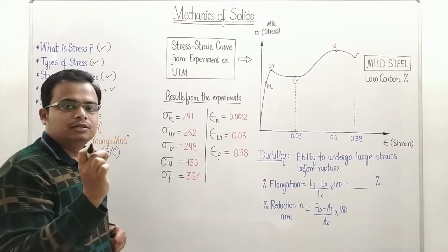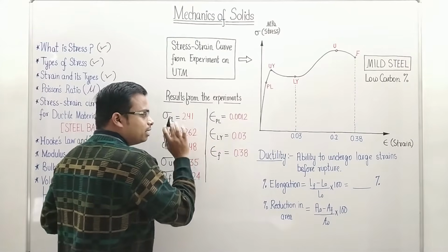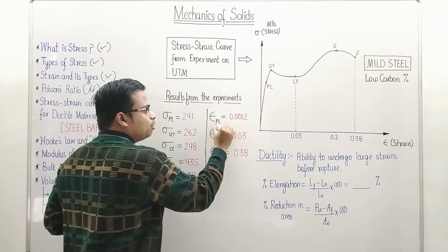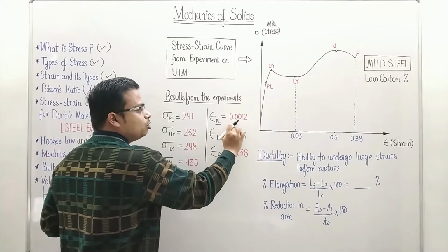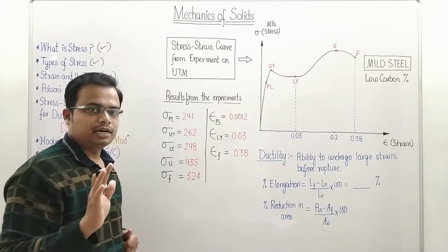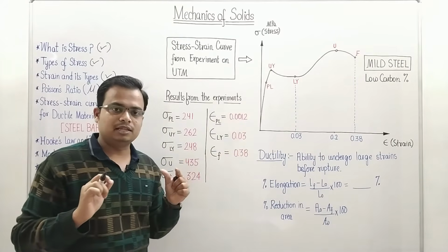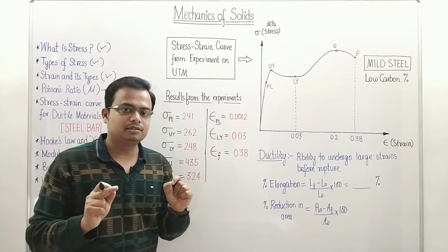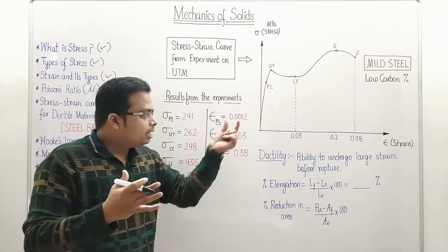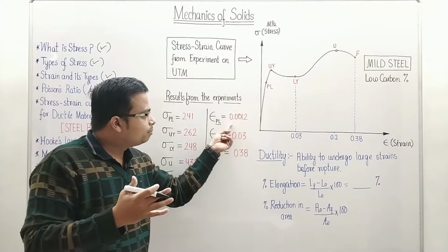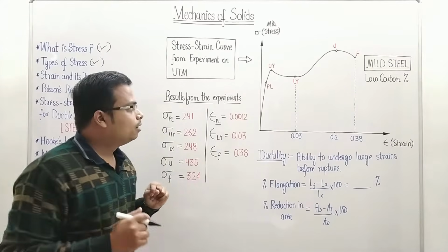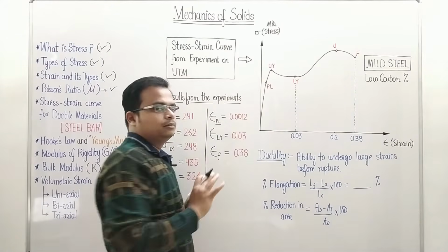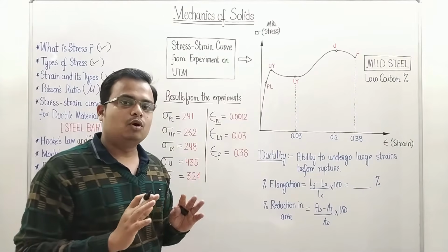to be some deformation. So before the elastic limit, or rather I should say at the proportional limit, the strain that we will obtain is 0.0012, okay, that is the change in length with respect to the original length. The original length is 50 millimeters. There must have been some change in length, and when that division takes place, you are going to obtain this value. Now, beyond this proportional limit, the material is no longer elastic.